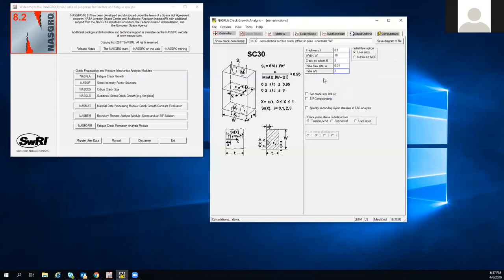NASA standard 5009 or different ISO standards do outline what the standard minimum detectable flaw sizes are for various standard NDE methods, and those were developed across a lot of different industry experts and their experience for what are reliable methods.